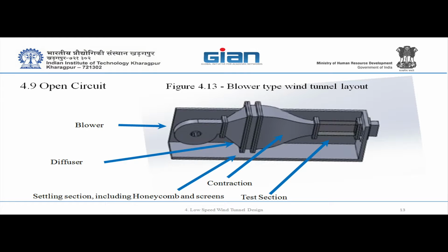But in terms of flow quality, you start with incoming highly turbulent flow, and you have to take care of it. That's why he doesn't care about this wide diffuser, because anyway, the blower there is very noisy, and then he has to take care of all the noise further downstream. Of course, in the Technion case, all the sections following the blower are much longer because he has to take care of all the noise.